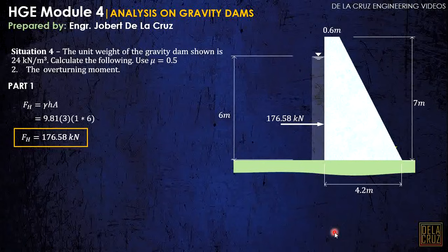Okay, this one, the overturning moment. Again, the overturning moment is what will overturn our dam. So, in this case, it's only the hydrostatic force. Nothing else will overturn this. Anyway, earlier in sample problem 1, we had hydrostatic uplift, no? Here, there is no specified hydrostatic uplift, so we will not account for it. Okay? So what is the analogy for our overturning moment?